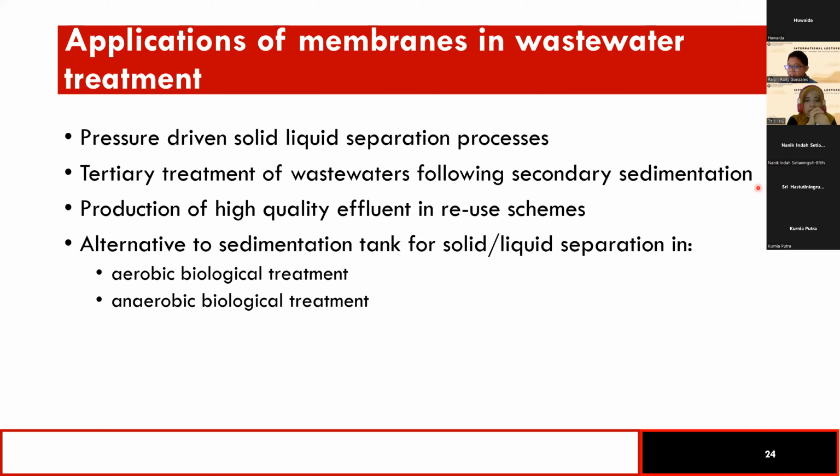Then the next process is secondary sedimentation, wherein they include some chemicals to further remove more waste. And we are left with wastewater which is only containing the dissolved solids. And this is where membrane technology comes into play. So tertiary treatment. After removing the bigger size particles, the bigger size waste, the wastewater is treated by membrane processes to remove the bacteria, the colloids, the suspended solids, etc.